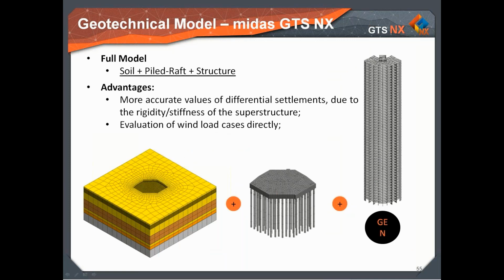So some numerical models of building foundations are made only by applying load or pressure at the base of the columns. It is like retrieving the reaction values for each column from the structure team and applying them directly to the model. This might neglect the redistribution of loads in the superstructure and its stiffness or rigidity, as you wish. So those results differ from the real behavior of the structure, showing higher values of differential settlements.